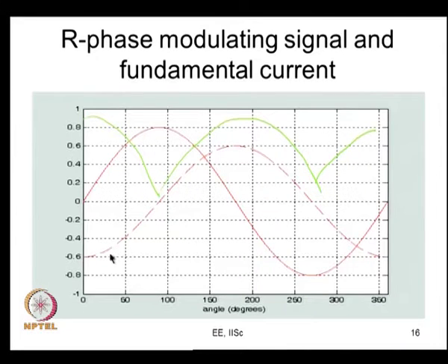We are looking at sinusoidal PWM, first sine triangle PWM. So, there is a load. Now, the average value depends on what? It certainly depends on this peak value. What does this peak energy loss depend on? It depends on the peak current. So, if the peak current goes up, then this will also go up, and its average value will go up. So, the switching energy loss certainly depends on the peak value of load current. That is very clear, it is just common sense.